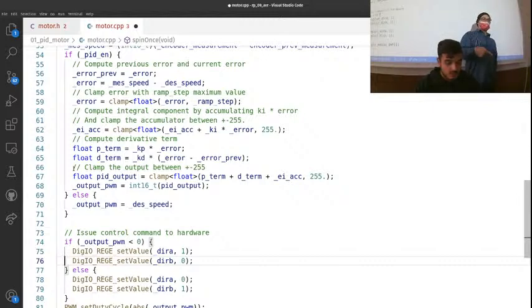When the measured velocity of the wheels doesn't match the velocity of the vehicle that you're predicting. In this case, if you're braking, once the ABS kicks in, you get back on the pedal. It's releasing the brakes, and by releasing the brakes it enforces the wheel to get the natural grip and get the speed back.